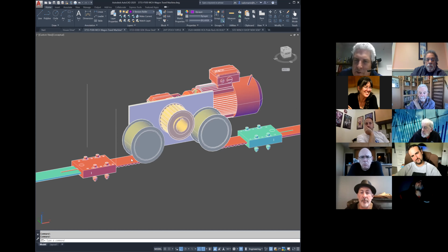The application I'm showing here is a little variation we actually have on the shop floor right now, where for a variety of reasons, mostly because we have these wagons that have all this other equipment in them, they move a very short travel, only about 5 feet. We chose to put the machine in the wagon so that we could keep the deck a little easier. So this machine is just a gear motor with a pulley on the output.